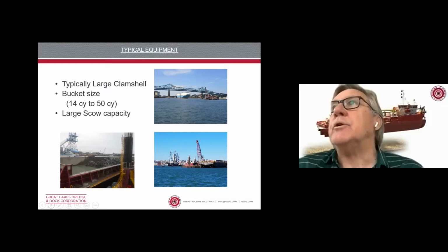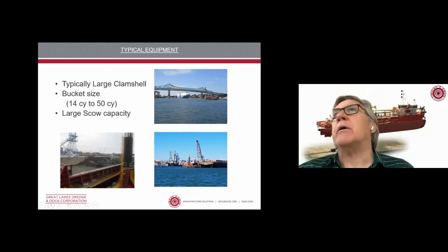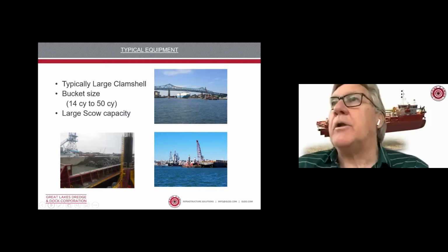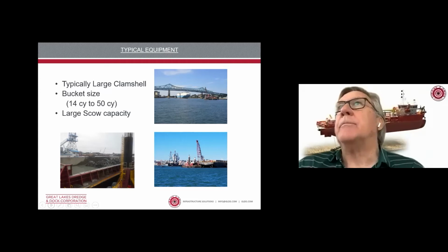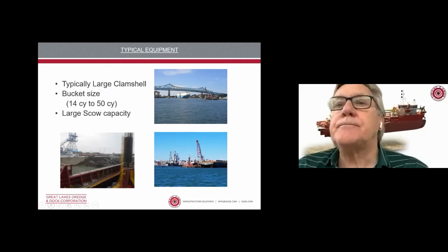The difference in the two is the weight. For order of magnitude, an environmental bucket of 50 cubic yards will weigh about 25 to 30,000 pounds, whereas a hard digging bucket, 12 to 14, can weigh up to 70,000 pounds. And that's just to help dig the harder material.